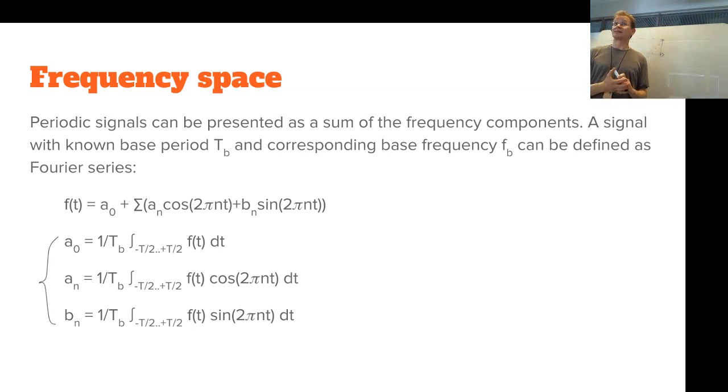Same thing for systems. Just like in analog systems, you did those horrific transfer functions in the S-plane. But then the spectrum analysis was really easy: you just replace the S with j omega. Done. Or you do the Laplace tricks to get the step response of the system. So don't be worried about frequency space. It's just a different representation of the same system or signal.